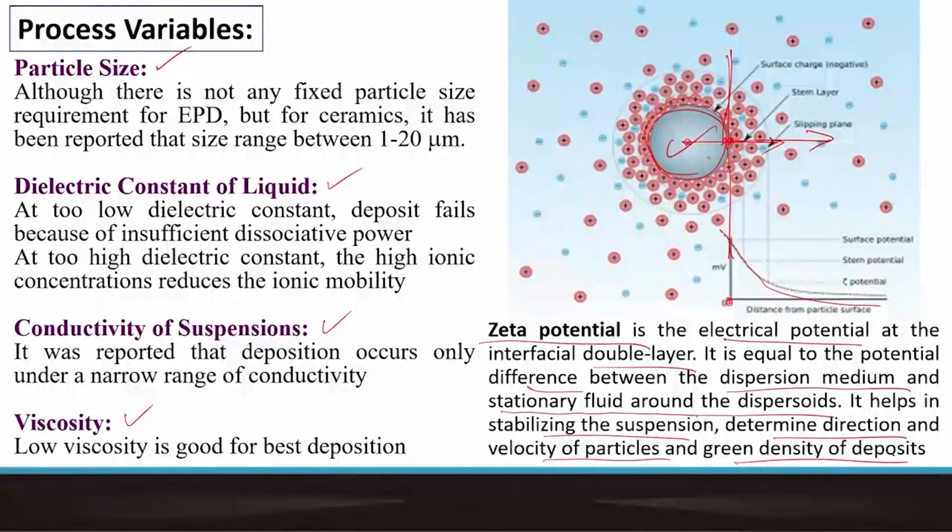So we are not depositing these ions, we are depositing this particle, which is a neutral particle. But the particle acquires surface charges and hence an electrical character. When we apply a certain potential difference, or because of the natural potential difference created by charge accumulation on this and some other parts which have less charge, these particles get deposited.